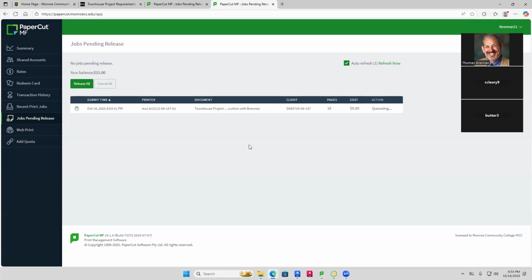I don't know how you said it, like cut off on level 2, level 3. Okay, this is your crop region. Crop region is something down at the bottom of your screen. It looks like this. Crop region always looks like that. Click on that, and then you just open it up. Grab the little blue circles and just expand around a little bit.